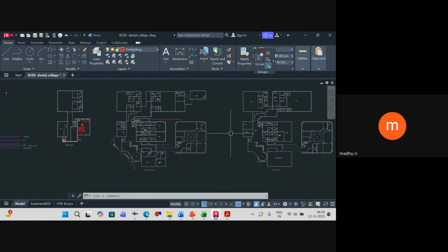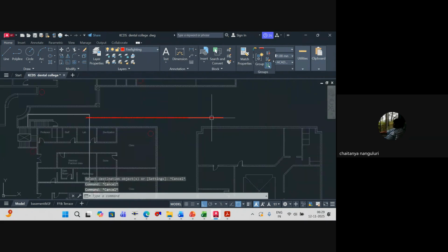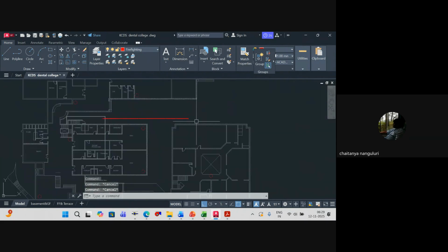Only one line will run, is it? And the sprinkler line won't run, is it? Only one line, is it? If I want, I can take 2 separate lines also. If I want, I can take 1 single line as well. If I take 2 separate lines, we can isolate it from internal to the pump room itself. If it is externally, if I want to do it, then we have to give valves at those particular locations. But by taking one line, how do you isolate the sprinkler hydrant, which we discussed? That's the reason I said we have to do it from the external of the building.